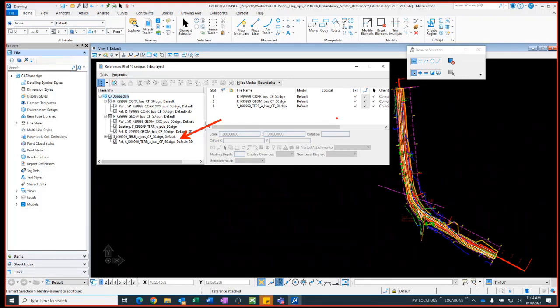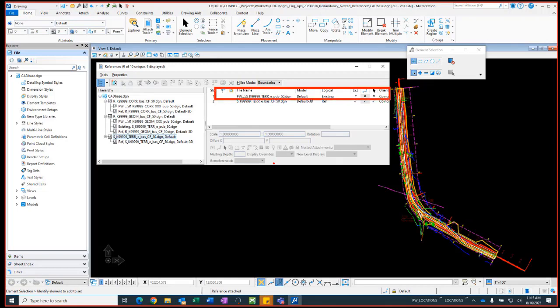Where am I going to see that redundancy? Well, this is one indication that I have a redundant file, the absence of the file in the hierarchy. It's not there. How do I know it's absent? Well, if I look at the container file, on the left-hand side, I select the container file. I'll notice on the right-hand side, I see the pub file, but I see the double quote, the ditto mark. It's a redundant reference.